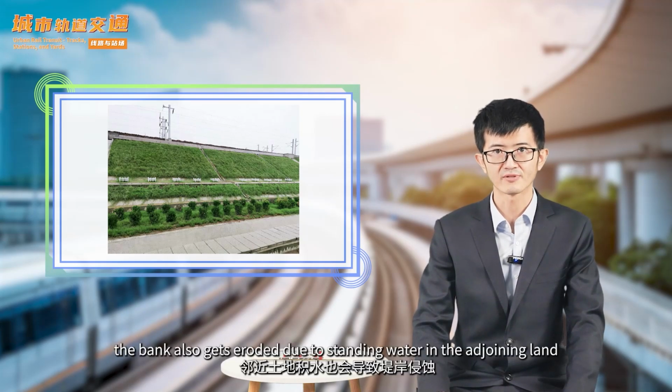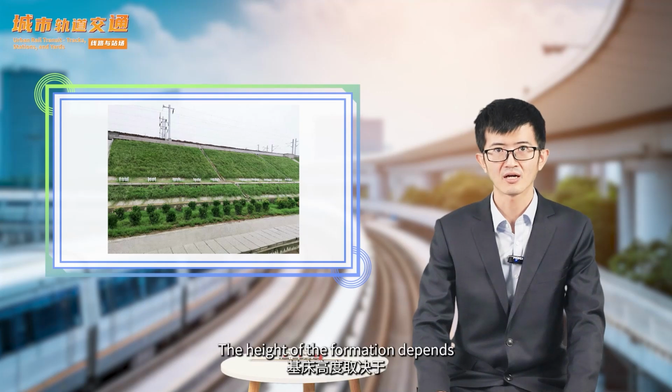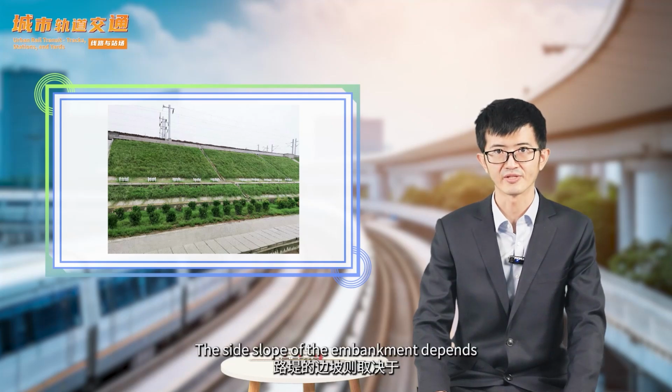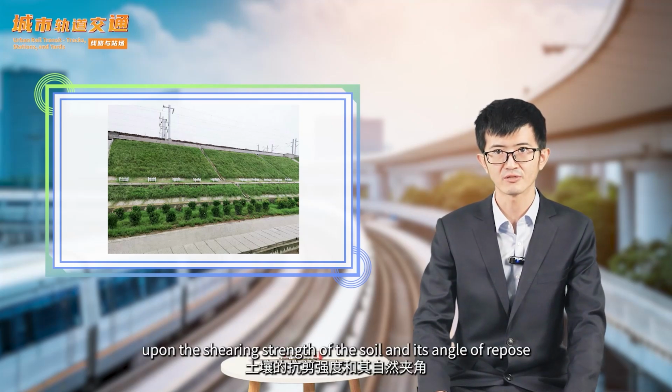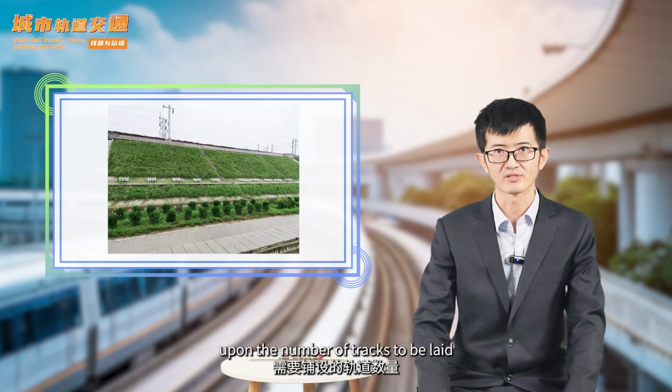Sometimes, the bank also gets eroded due to the standing water in the adjoining land. A toe and a pitching are provided in such cases. The height of the formation depends on the ground contours and the gradients adopted. The side slope of the embankment depends upon the shearing strength of the soil and its angle of repose. The width of the formation depends upon the number of tracks to be laid, the gauge, and such other factors.